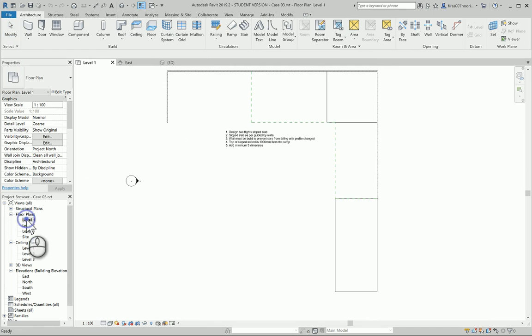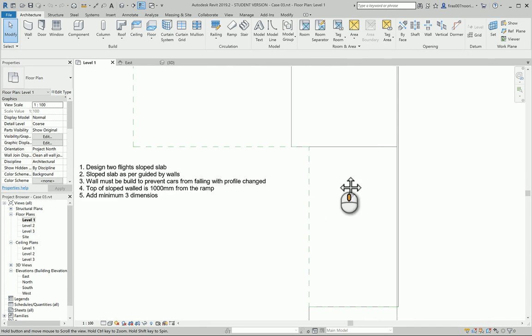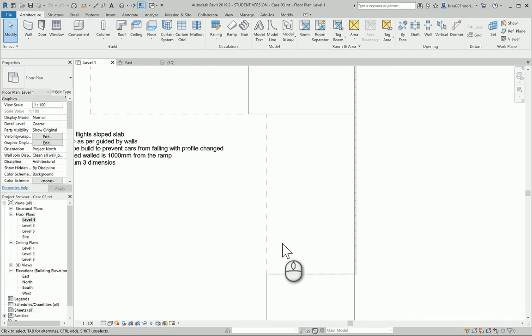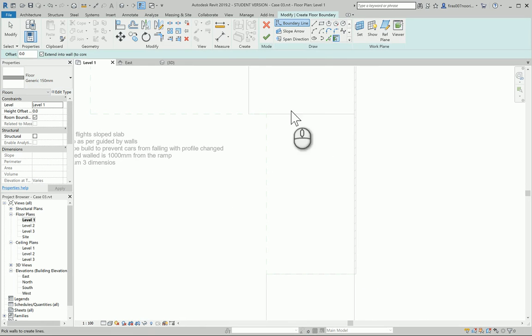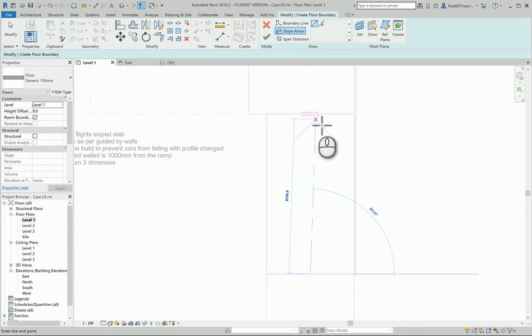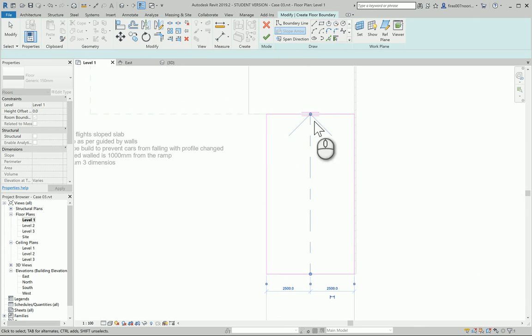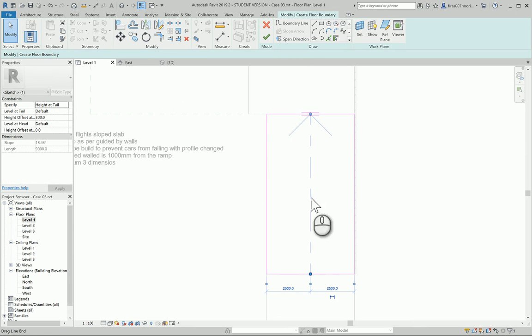Anyway, if I go to level 1, I dotted this area for you, so that will specify the location of the plan. Simply, you need to go to a floor, disregard the type, of course, and pick the lines for the boundary. Within the sketch mode, you might need to hit TR, or trim. Okay, get rid of the boundaries and then just lay the arrow as such to specify where the lowest point is and where the highest point is.